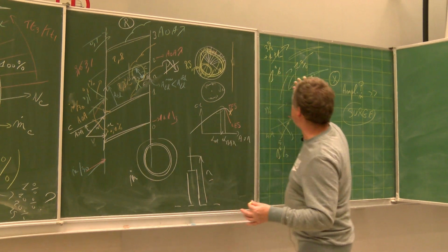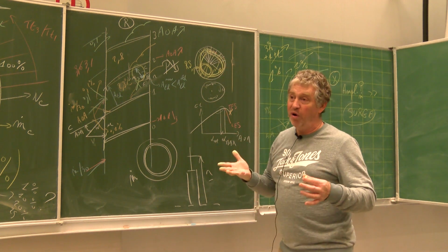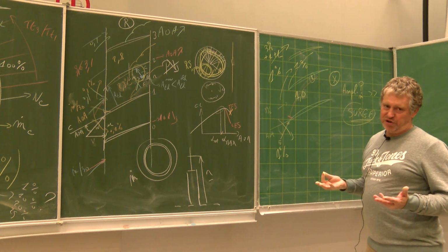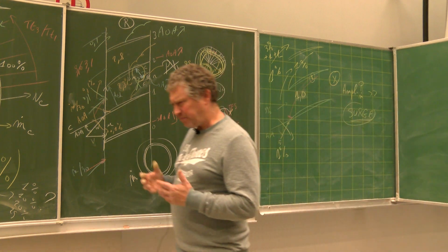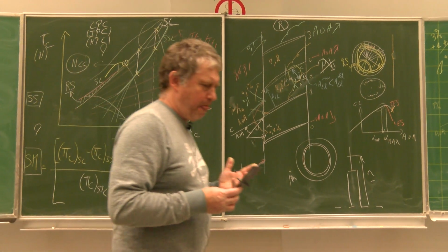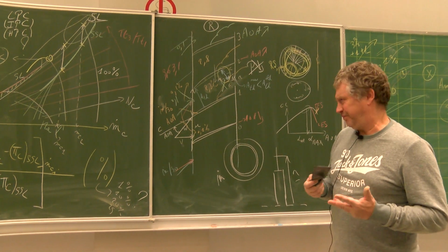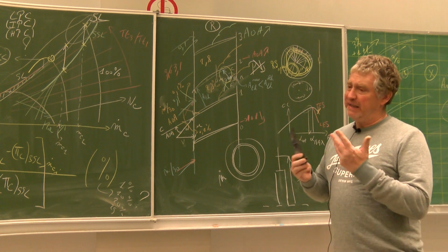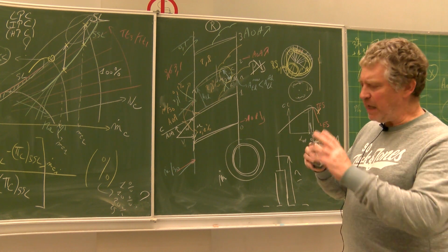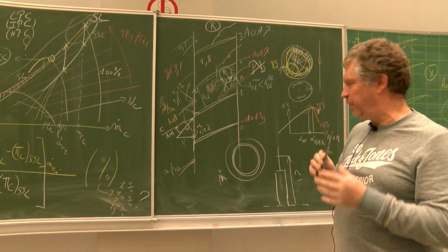It's not rotating because you are influencing the full problem, and it's not rotating anymore. It's also not called a stall because it's more severe than that. And this is what we call a surge. And what is leading to the fact that maybe the same problem originally is becoming a surge instead of a rotating stall? There can be a lot of reasons, but one of the reasons is certainly the dimension of the blade.